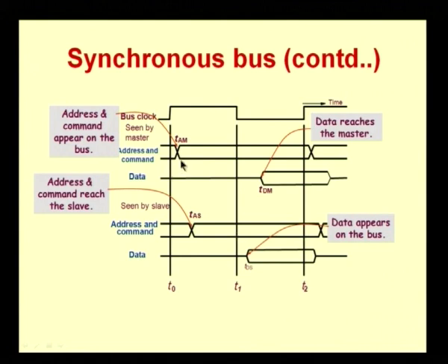Okay. This is when it will actually appear on the bus. So, it will appear on the bus, and it will have to be on the bus, as we said, for a little time after the data has been strobed in. So, you can see that this value remains on the bus until the end of the clock, and also for a little bit of time after the clock. That is what you need to remember over here. So, this is placement of the address and data, address and command.